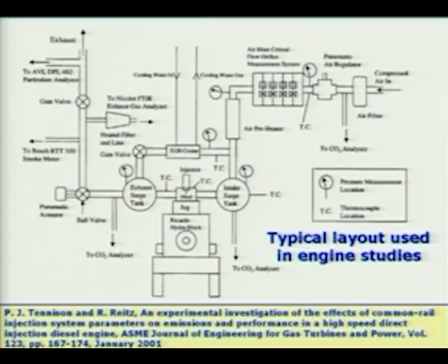That means that you have many channels and all these inputs go into the various channels of the data logger, and the output is recorded almost on a continuous basis with respect to time. And the other advantage of that is that the data can be saved into a computer, and the analysis can be done by using a program which you can develop or available programs, and then you can analyze the data at leisure after conducting the experiment. The experiment itself is conducted in a very short period, and the processing of the data takes place later on.